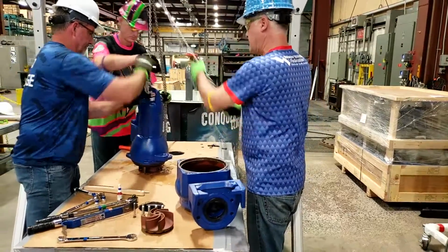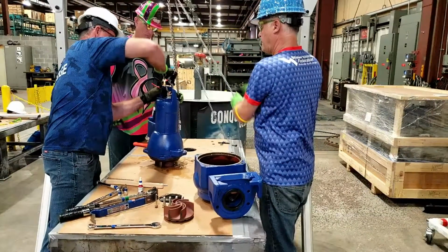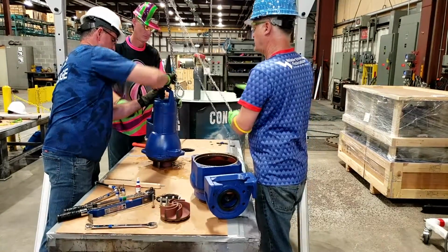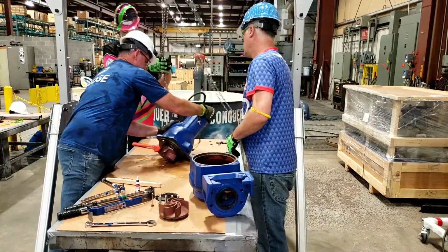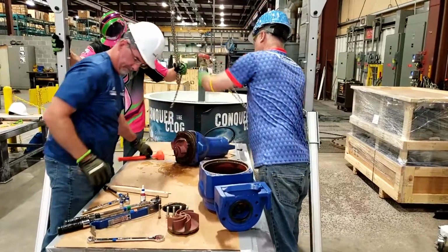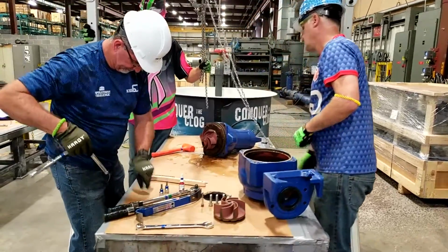You may slide the volute. This also must be done over the table. You cannot carry the volute off the table to move it to a different location on the table. Once the pump is back down on the table, you may disconnect the hoist. Remove the 6mm impeller hex socket bolt.